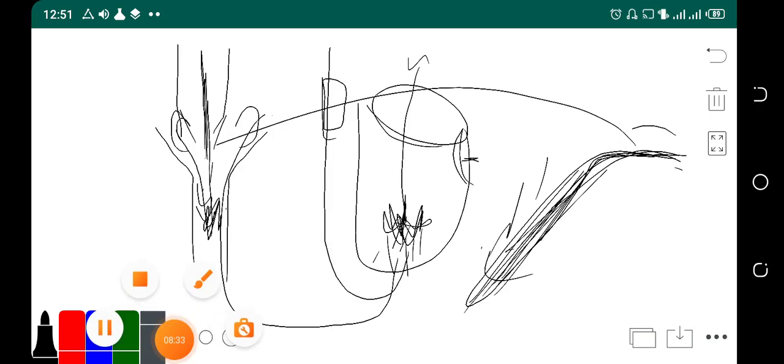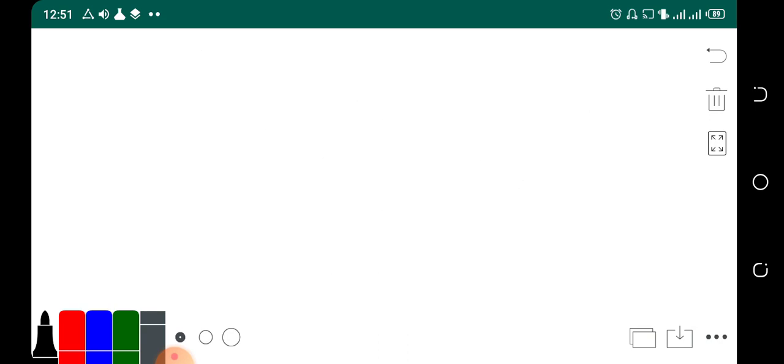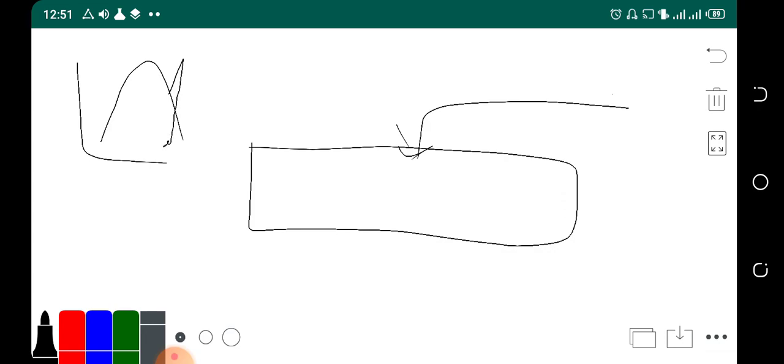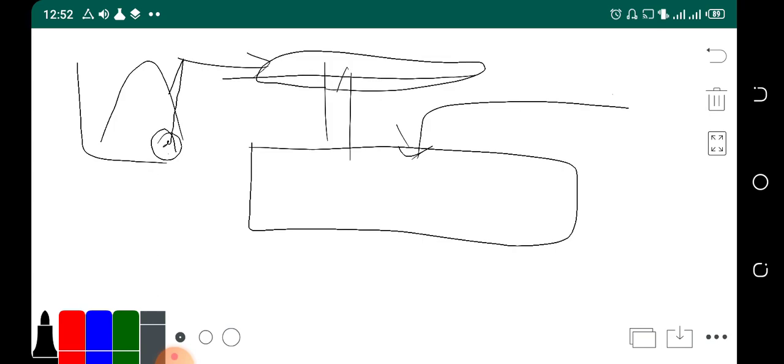Another example is the condenser. When the steam comes into the condenser, you see in the steam table that after the turbine, the steam comes over here in the saturated liquid-vapor state. So we can utilize some of the vapor by using a nozzle over here with high velocity steam. It produces vacuum, so it sucks some of the flash steam along with the steam, and then this steam is utilized in some other process of heating or reheating, or it can go towards the low pressure turbine.